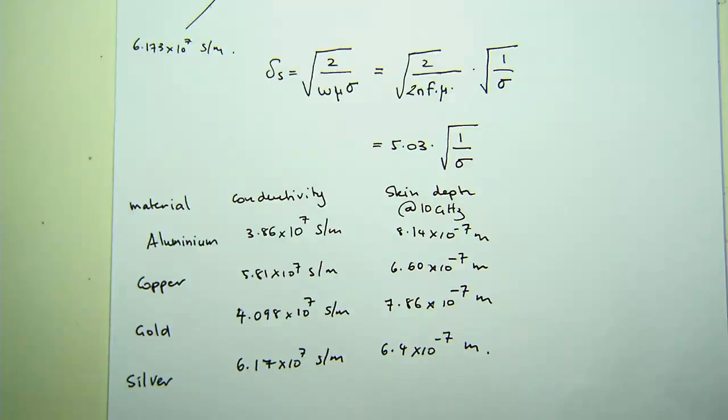Just electroplate a thin film of gold or copper or chrome on the surface, and you've got a beautiful, immaculate little antenna or waveguide or Wilkinson power divider. So all of a sudden, as you go up in frequency, the skin depth is so small, it means you can just electroplate a little bit of plastic, and you can start making some really cool stuff. Or at least it's cool to me.